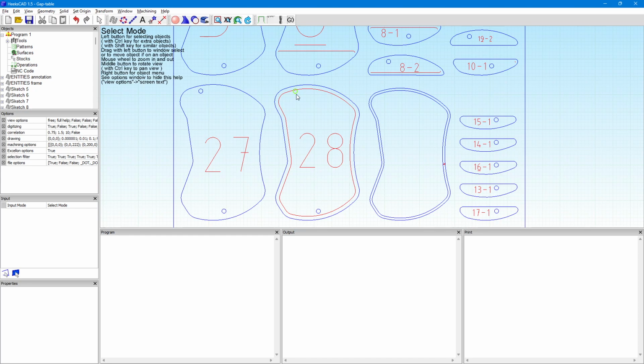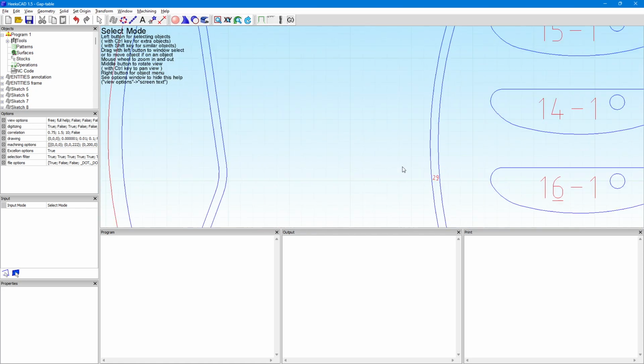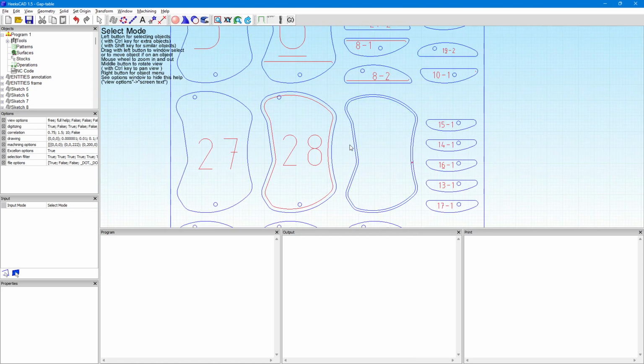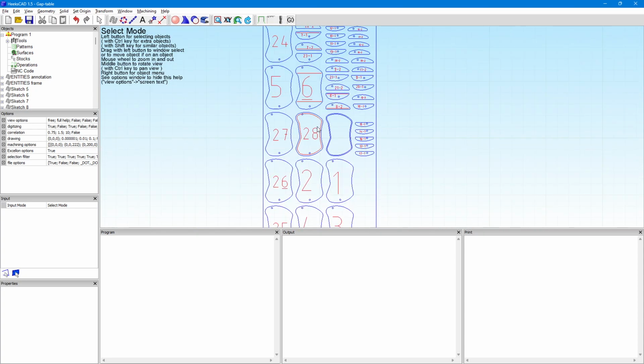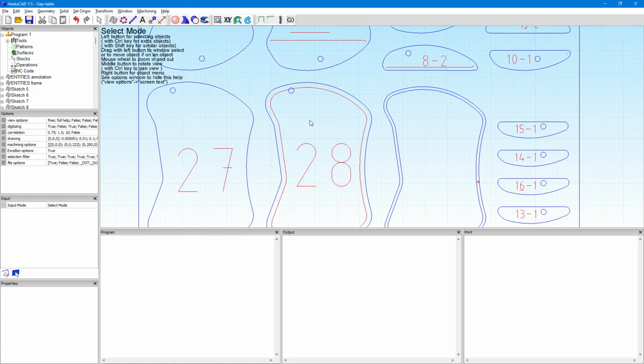Here I got a problem here. Can you see why it's red? Because the dowel pin is going through the cutting, and that's why it's showing that there is an issue here. Okay, and this one as well. So these two parts are thin profiles, so we need to have a specific operation for this.